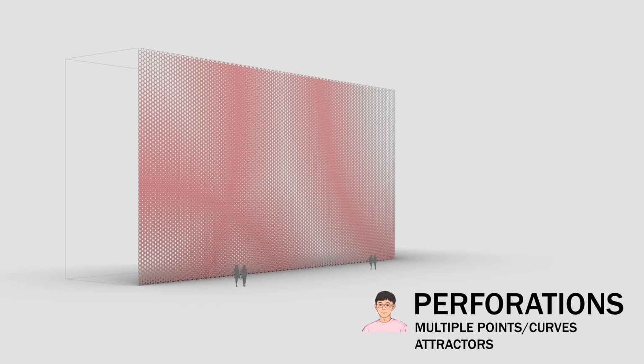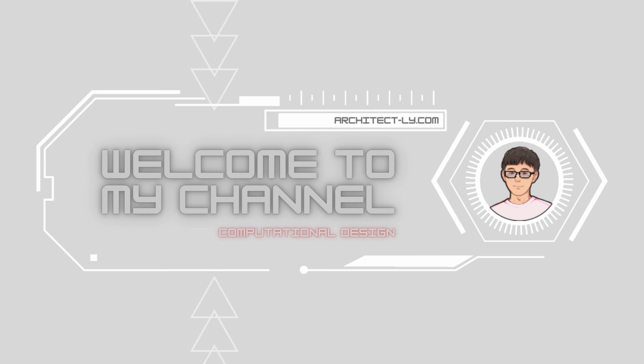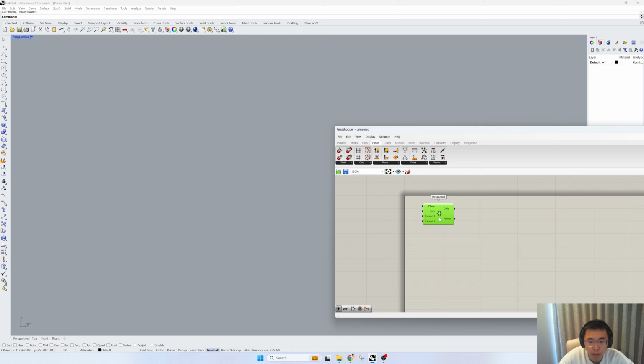Today we're going to talk about the hexagon perforations with multiple points or curves to affect its patterns. Alright, let's start. So the first step we're doing is to introduce hexagon grid. Then the size will be 100. Extend will be 100. And then we have another 50 to the Y direction.